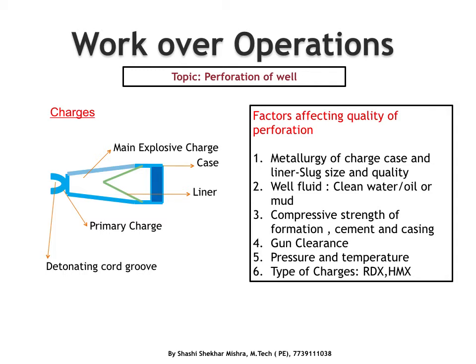Then also the pressure and temperature influence the perforation. If there is a higher temperature, then we have to go with different charges that are designed for the higher temperature, and charges for higher temperature provide less penetration. They also have less sensitivity, which increases the chance of misfire.